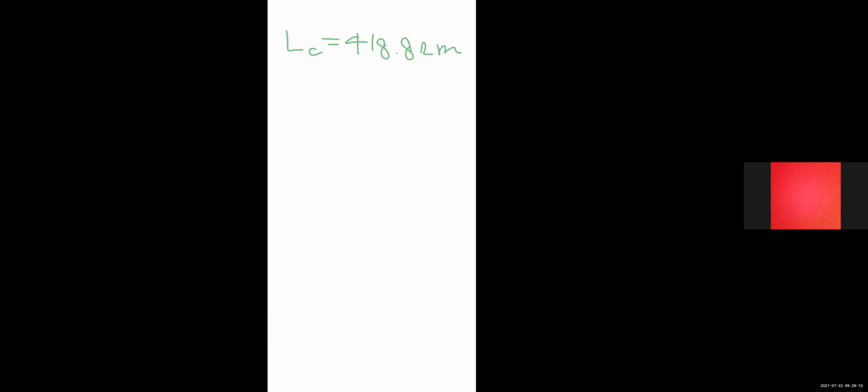Also tangent distance. For calculating tangent distance, that is the distance between PC to PI, also distance PI to PT. This is the tangent distance. So T equal to T1 V, also T2 V equal to OT1 tan delta by 2. OT1 equal to R, so R tan delta by 2. R value is given, delta value is given.